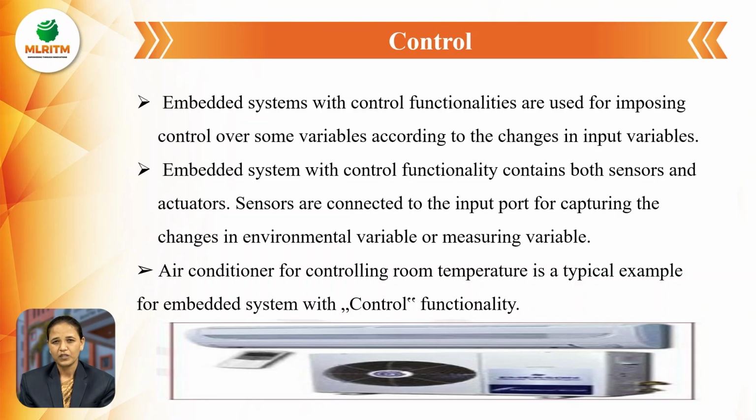If the temperature is below 20, then the temperature sensor in the AC does not respond to the temperature at all. Here, at below 20 or 30, the sensor is not working and is not indicating any information to the microcontroller. The purpose is that when the room temperature increases, only at that time is the sensor activated. If the room temperature is low, it does not pass any information to the microcontroller.